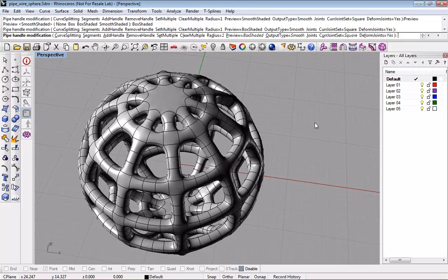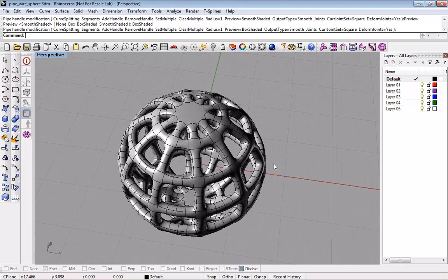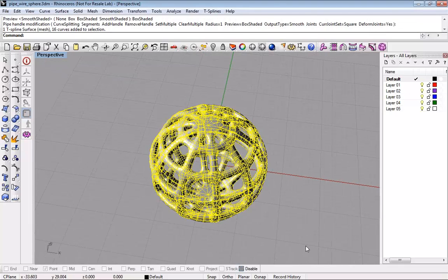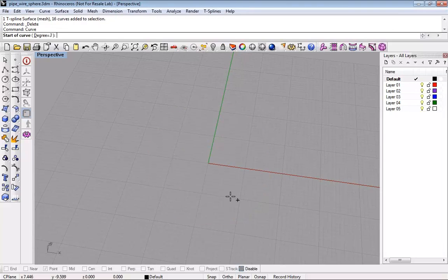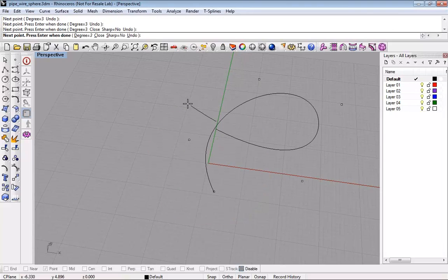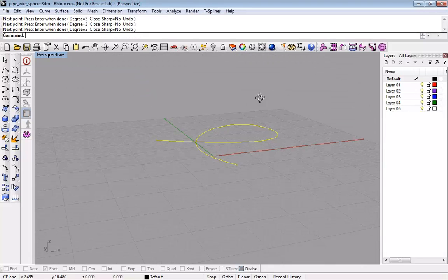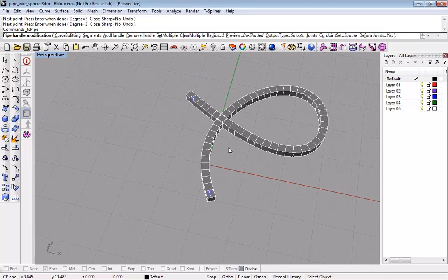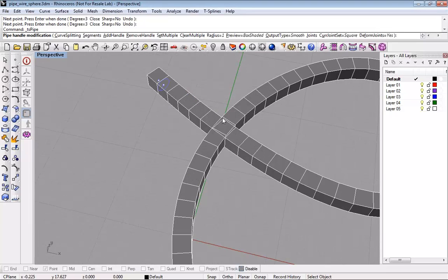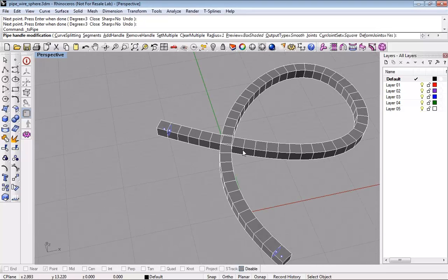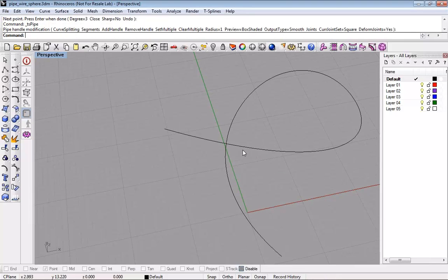Yeah, I'm not sure. It's been a while, honestly, since I've reviewed that code for the curve-curve intersection. We could do a quick test. So this curve does intersect itself. We run the tsPipe command, and it looks like it does not check for curve self-intersection. So you need to split that into 2 different curves for it to be able to automatically detect that.